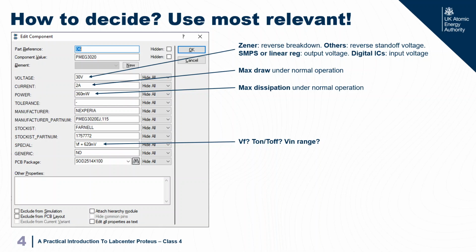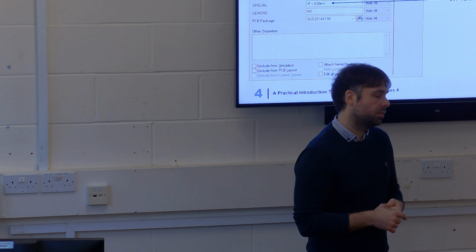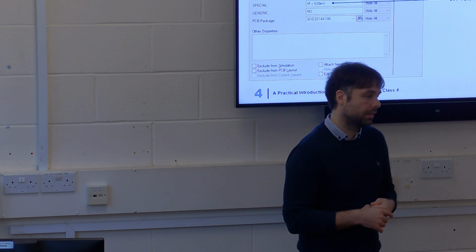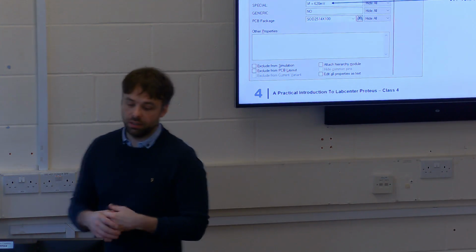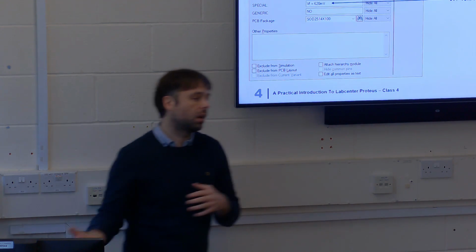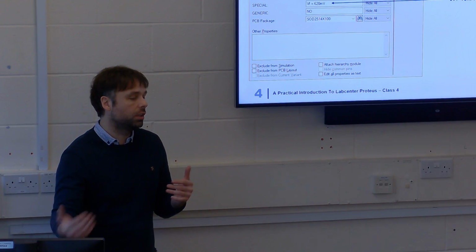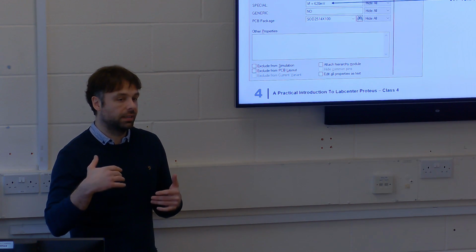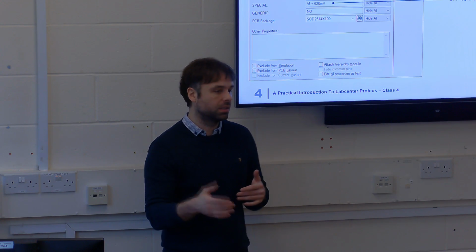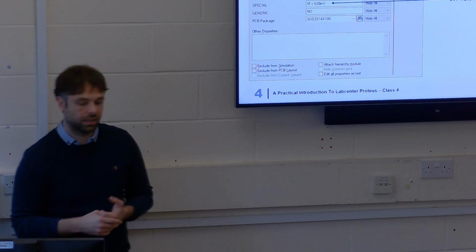What about a rectifier diode? What would be the most pertinent voltage of a rectifier? I would say the forward conducting voltage. It's either that or the reverse breakdown. Essentially it's the same voltage parameter. But in your Zener diode, you're constantly using it in the reverse breakdown, whereas in a rectifier, you never really want to exceed that voltage, because that's what it's there rectifying.